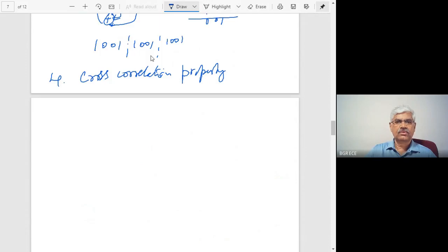So this is how the code that we use for spreading the spectrum requires to satisfy randomness properties, so that it will allow you to camouflage your signal as a random signal. It will allow you to detect your original data using the autocorrelation property very easily, and it will allow you to use it in a multiple access environment.